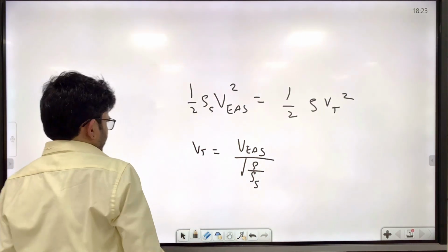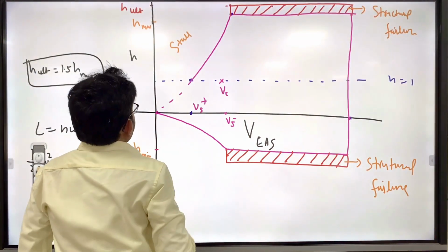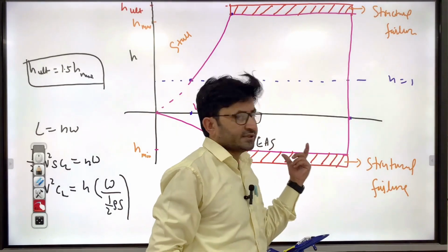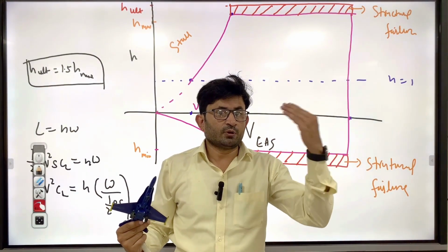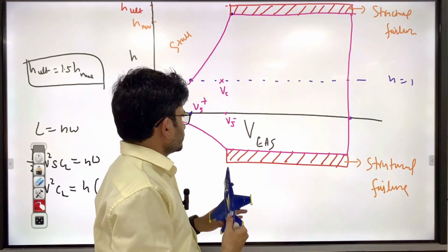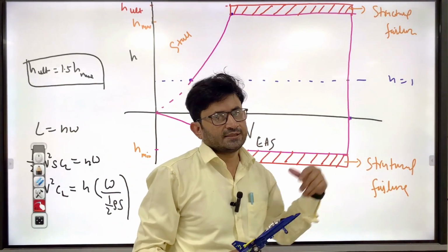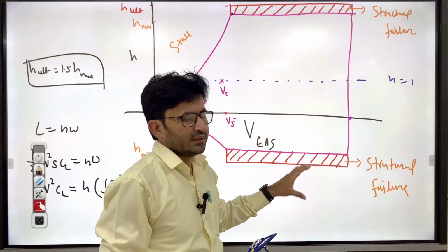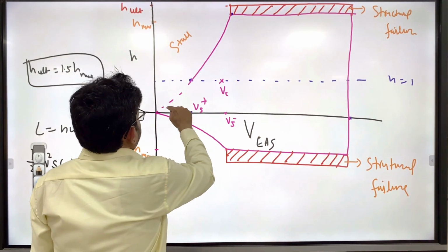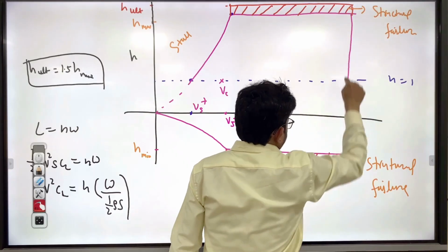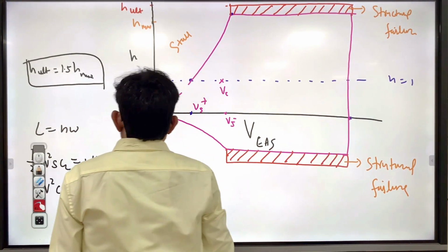So if you want to plot the VN diagram between load factor and speed, and you consider the true air speed, you have to draw multiple VN diagrams, because the moment you change the altitude, the speed will change. In order to solve that problem, instead of taking true air speed, you take the equivalent air speed on the x-axis. So you have to draw only one diagram. That is good for pilot understanding also. Now, you can see this line, this line, and this line. I will explain each and every line. So load factor and equivalent speed, clear.